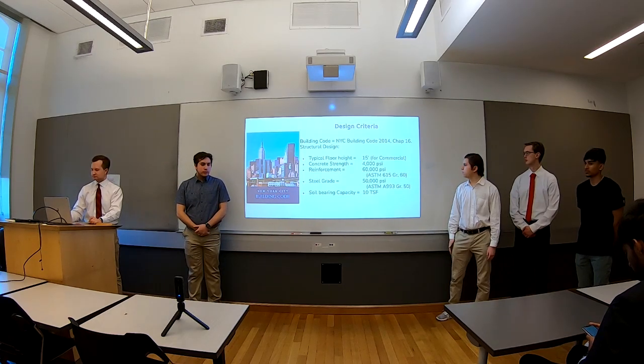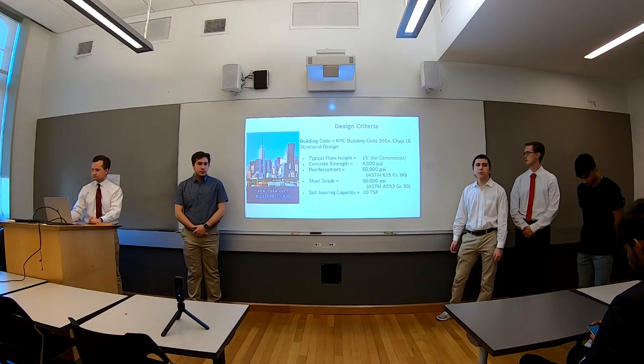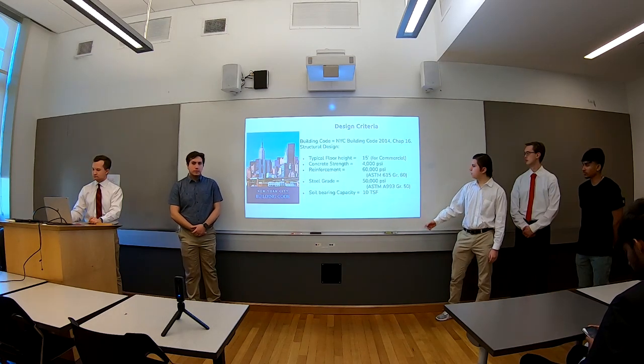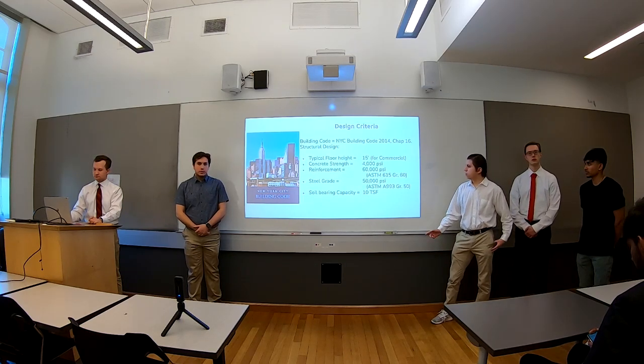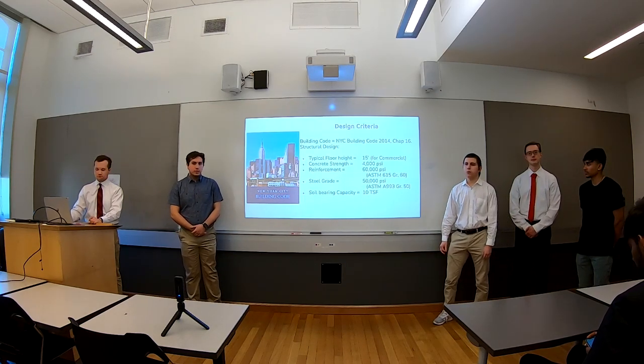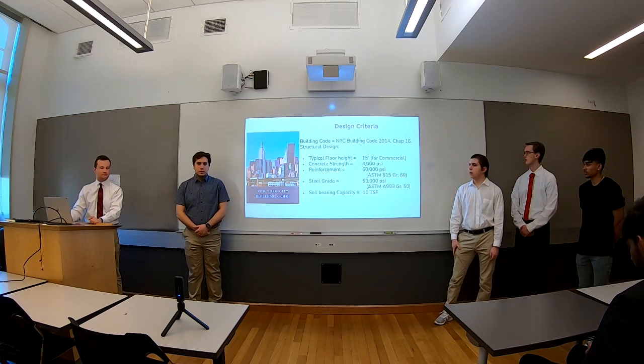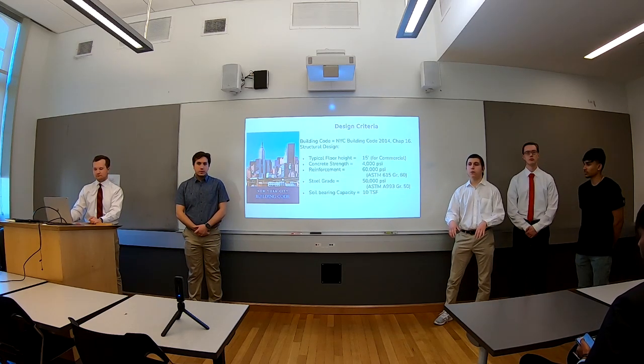All our steel beams had to be 50,000 psi, and this is equivalent to the ASTM standard A992 grade 50 bar. And lastly, the required soil bearing capacity was 10 tons per square foot, so this is important when we figured out all the loads going down into our footings.